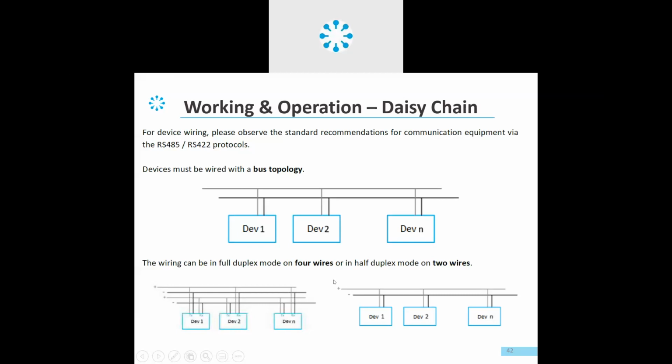In inverters, we normally have data in and data out, so it's quite easy to understand from where we have to take the chain in and from where we have to take out. But in meters and sensors, we don't have data in and data out. We only have one data plus and one data minus port. So you have to make this sort of arrangement: data plus, data minus, and then again a wire going out from the same terminals, data plus and data minus, and connected here.